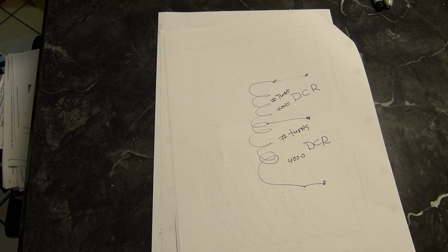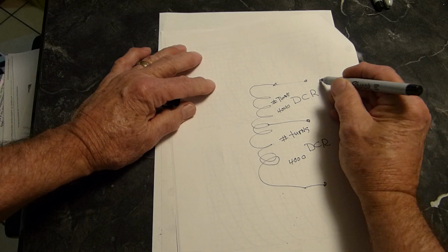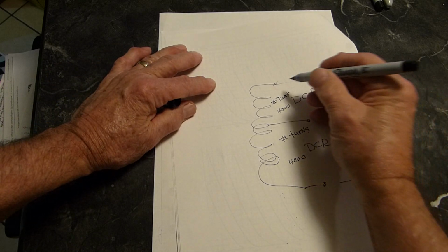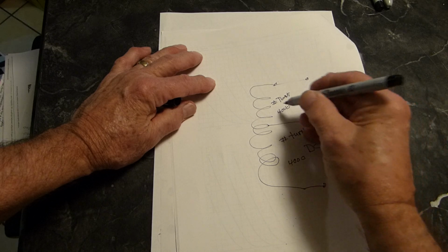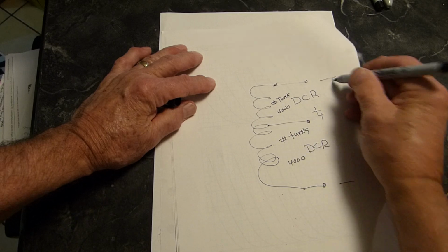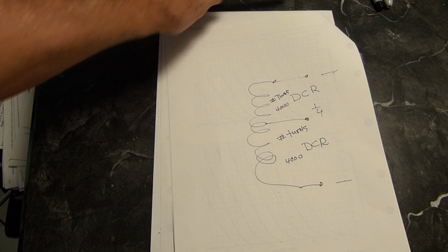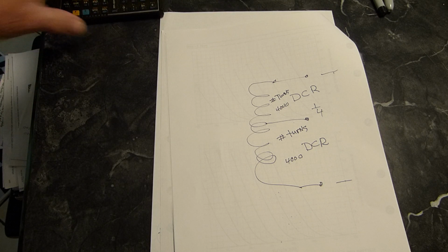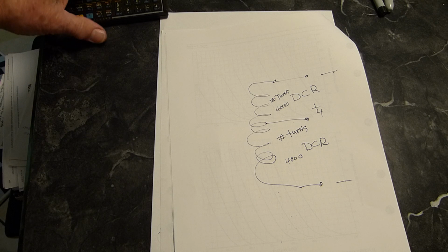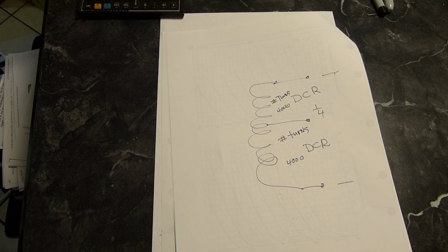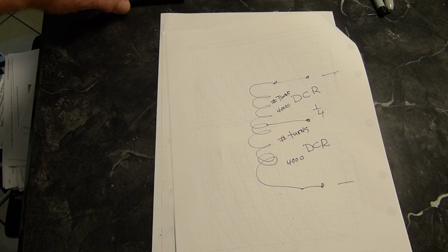And if you measure the inductance, it might actually measure ever so slightly different. But don't forget that part right here, that this and this, from here to here, and here to here, is 1/4 of the inductance from here to here. So keep that in mind next time if you are stressing over how many henries you need in your output transformer, and especially SET stuff that people get really obsessed about.